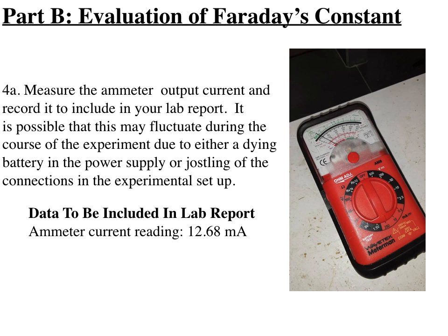But what I'm going to assume here, and I did monitor this, as long as you don't touch it very much, and you have a pretty good, steady battery, I monitored a current of 12.68 milliamps running steadily during the time of my experiment. So this should be a number, again, that you should indicate in your write-up as to the current that was flowing through the circuit for the duration of the experiment.